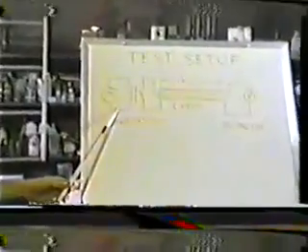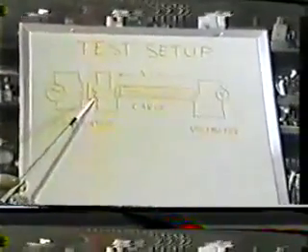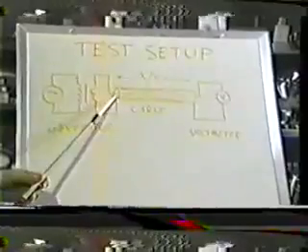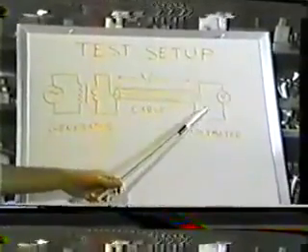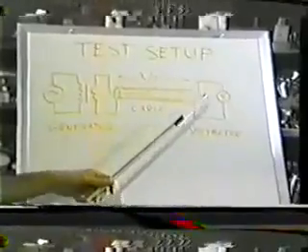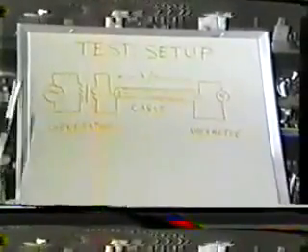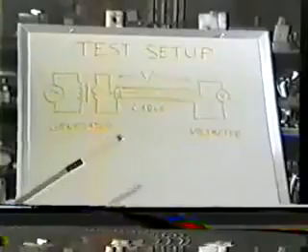In our study of electric waves, we're going to start with the well-understood transverse electromagnetic wave, and we're going to do some measurements here to determine the characteristics of such waves. To start with, we'll have a radio frequency generator and a step-down transformer to drive a long section of coaxial cable, and then a high impedance bridging voltmeter to measure the rise of electric potential due to resonance at the distant end of the cable.